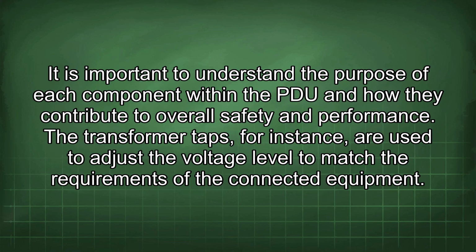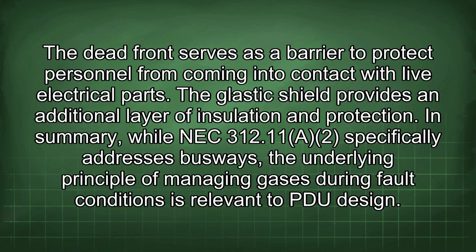It is important to understand the purpose of each component within the PDU and how they contribute to overall safety and performance. The transformer taps, for instance, are used to adjust the voltage level to match the requirements of the connected equipment. The dead front serves as a barrier to protect personnel from coming into contact with live electrical parts. The glastic shield provides an additional layer of insulation and protection.